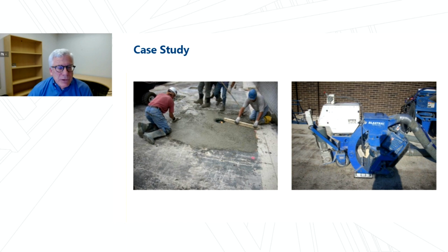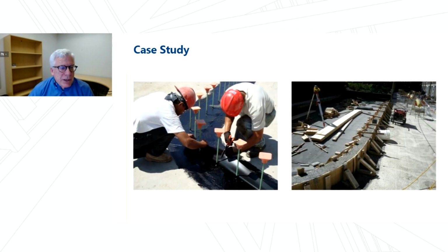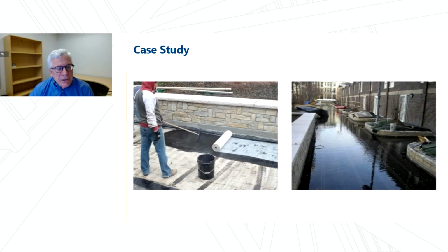Then laying out the new concrete. Once that's done, remove all the remnants of the previous waterproofing, and then surface preparation, like Jason explained, with the shot blasting, and then using that curb technique that he just talked about, pre-treating around where the curbs are, placing the curbs above it, and this is for the planter. And then in this particular case, they're doing a hot applied system. It was being flashed, and then on the right, it was waterproofed. In today's world, this would probably be low voltage tested.